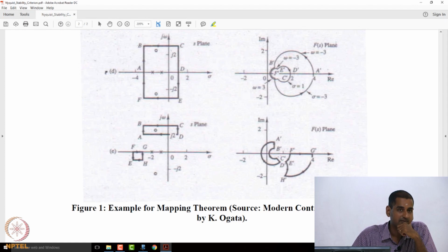If N_C is equal to say 3, then you still have just one contour. Taking the f of s point here and mapping it to the f of s plane, you still get just one contour, but it would have encircled the origin 3 times. That's why I'm saying please do it and convince yourself. Because we cannot do it by hand, you need to use MATLAB or any other numerical tool to generate the contour. So that's why I'm saying kindly program. I'm sure you guys can do that.